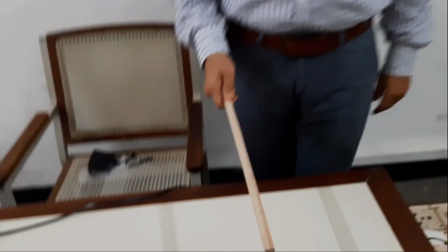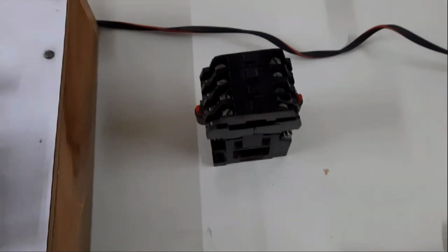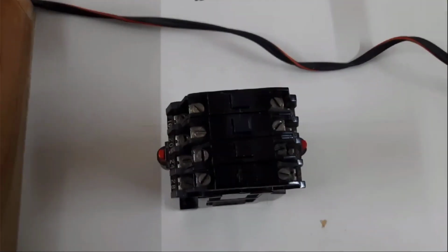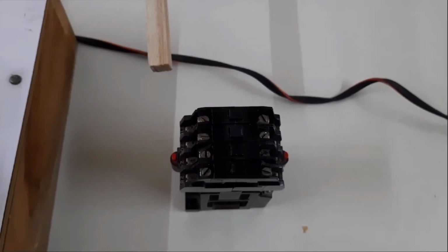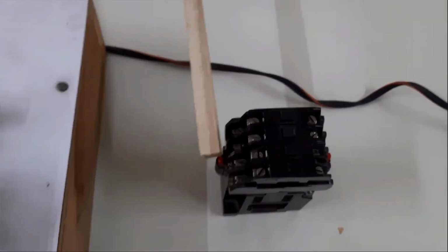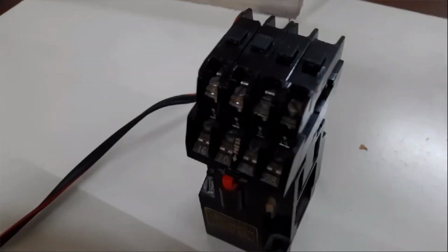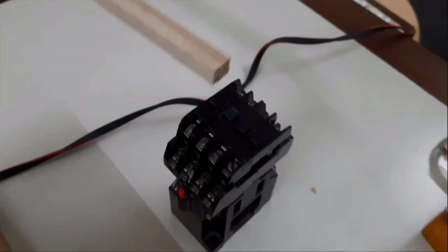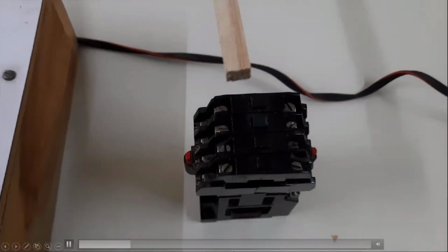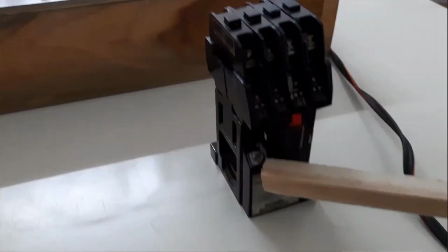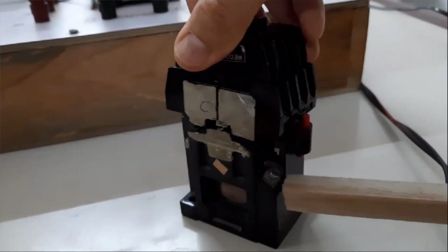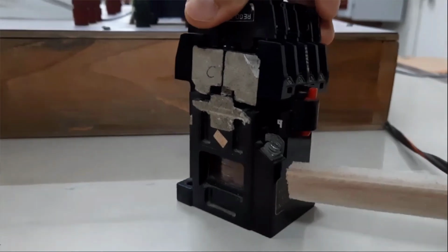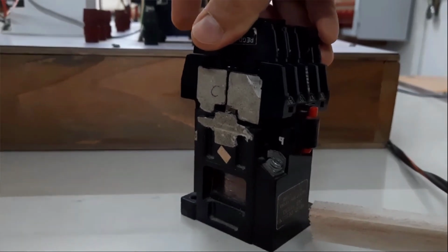So now let us concentrate on this piece of article. The thing what you see over here is nothing but the contactor. This contactor is a three-phase contactor, in a sense that one side there will be incoming, other side there will be outgoing. Now, here at the top you see there are some indications whether the contactor is on or off. Now, on the side of the contactor, here where I am pointing, this is the coil. This is the terminal of the coil. So this is the first terminal, and on the opposite side there will be another terminal of the coil. So there are two terminals of a coil. A coil is single between all three phases.